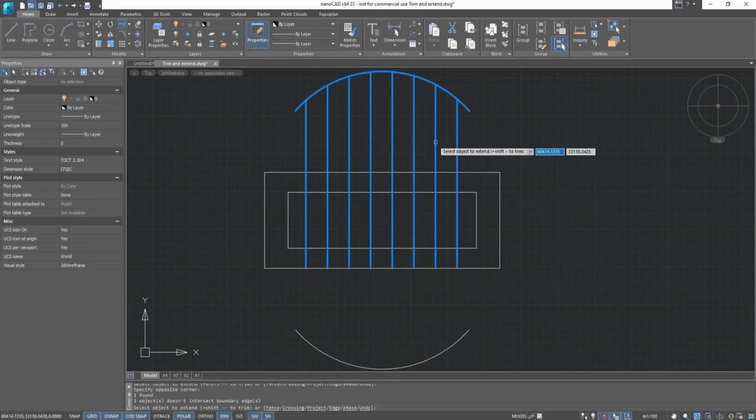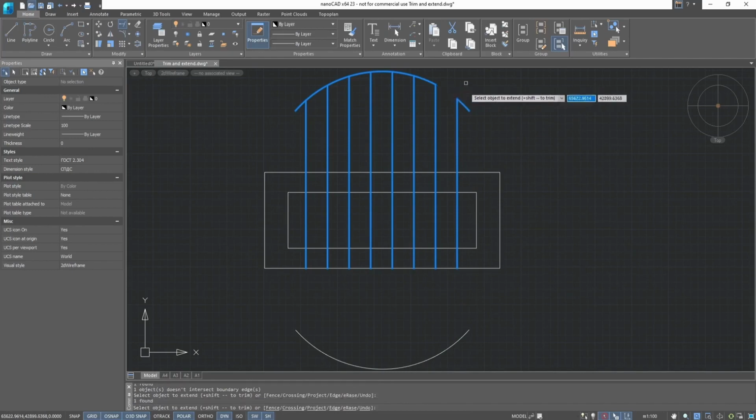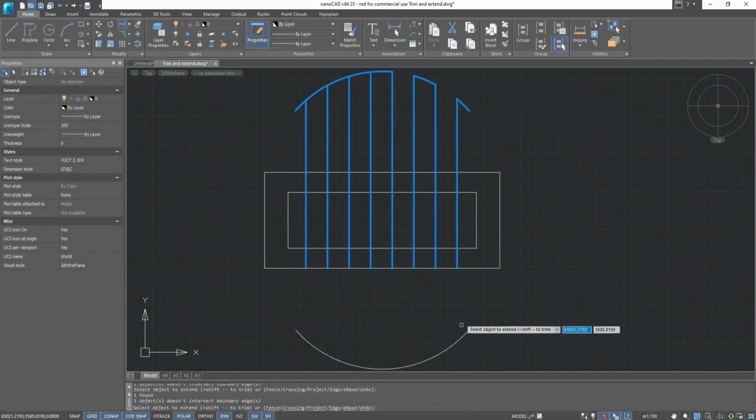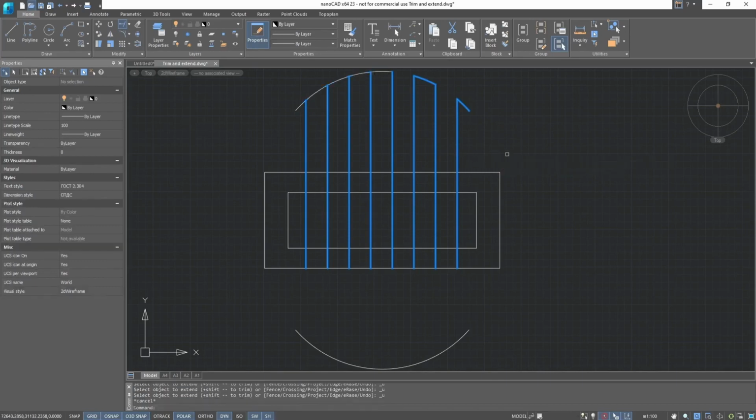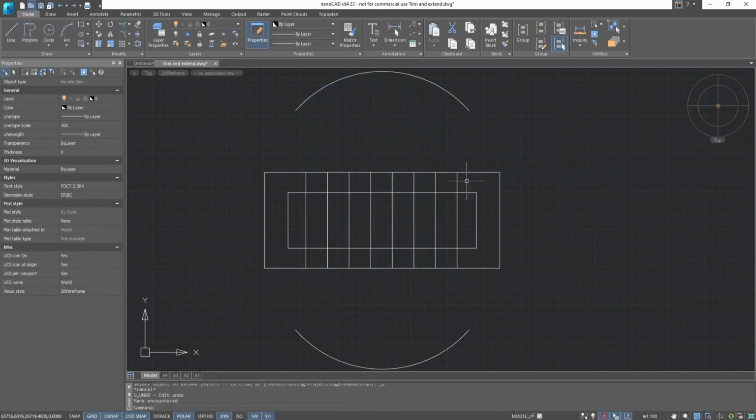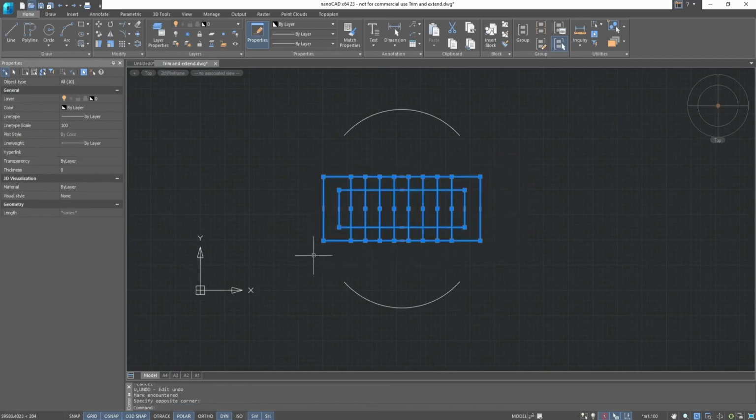And, as mentioned earlier, if you press the Shift key, from Extend we can switch. Edge is not selected here, so trimming doesn't happen. We can switch from Extend to Trim, and vice versa. Undo the actions. Also, if there are several boundaries, in this case 2, then extension will occur from the side closest to the mouse cursor direction.